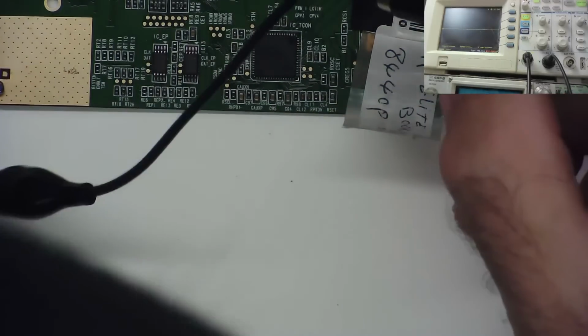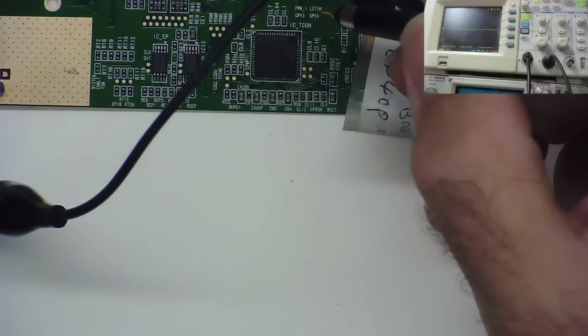Okay, so I've now got the bench magnifier, so I can actually see what I'm doing without shorting anything out. This might not help you, but it'll help me to get the oscilloscope probe on and hold it on there. Okay, so let's have a look at one of the outputs. Yeah, there's one. And you can see I've just got the same noise on that, whereas on the other chip, I actually had data coming out. Oh, there's data there.